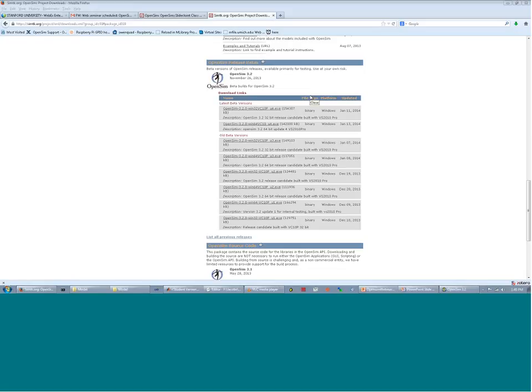Yeah. So there have been some users who have tried to automate that transition from CAD to OpenSim. And as far as I know, there's nothing in there directly that lets you do that. But as you saw for the contact mesh with the foot, there is a way to import small objects. So I would say if you have a linkage or some other element that you really want to use as a body, you can definitely import that if you have an object file.